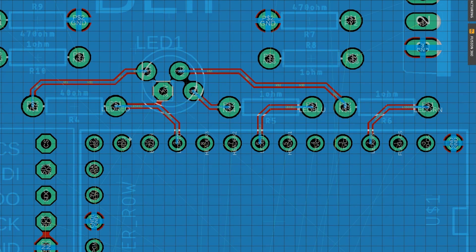It's kind of magic how that happened so quickly. But what you'll notice is that I actually flipped the resistor for the red LED 180 degrees so that it would be even closer to the pin it's connected to, pin number 9 on the Teensy. So I reconfigured the other pins for the LED, and now that part of the board is routed. This is sort of how PCB design works. This is, again, a gross oversimplification of the whole process, but it's not too bad. You start out by placing things where they seem to make sense, and then as you learn more about the board and how your routing works, you can change the design as you need to.